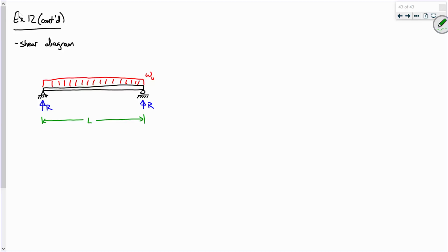Okay. Now, help me out. If this was a structural analysis problem, you tell me what to do. Solve for the reactions. And what are one of the things that I do with that distributed load to make my life a little easier? There we go. Convert it into a single point load. So I'm going to say that single point load is probably something about like that. And what is the magnitude of that single point load? W times L. And this distance right here from there to there is, there we go.